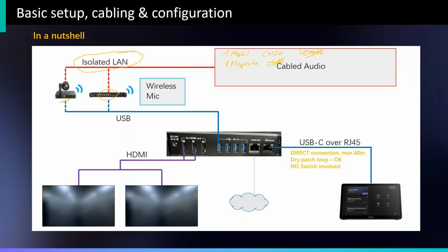hub, for example. We need multiple AV hubs in such a divisible room. But there is a master AV hub, and the other ones turn into switches when they are slaves. And the master AV hub then has to be able to cater the maximum amount of devices in that merged room. We have wireless microphones, DECT microphones, and Wi-Fi microphones.